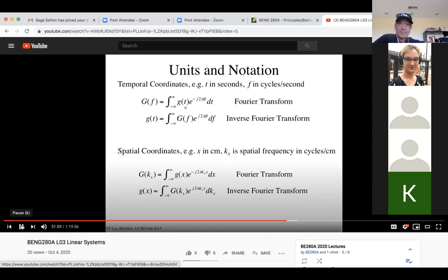So anyway, if you have the Fourier spectrum of the object, you can recreate the time domain signal by taking the inverse Fourier transform. For imaging, all we're doing is saying, I have a function in space, and the brightness of my function changes as a function of x, so it gets bright and dark, oscillates up and down.